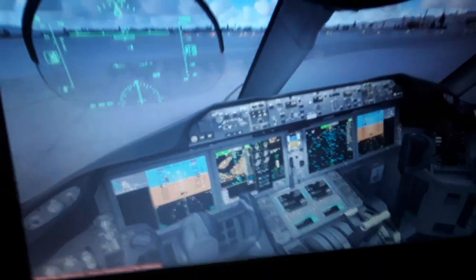I'm going to show you how to tune the frequency and use the ILS localizer both for takeoff and for landing. We have also the flight director crossbars for manual guidance of the aircraft and the autopilot crossbars for automatic guidance of the aircraft, the angle of attack of the aircraft as it flies, and the flight mode annunciator, with the autopilot and the autothrottle. Later on, vertical navigation modes.